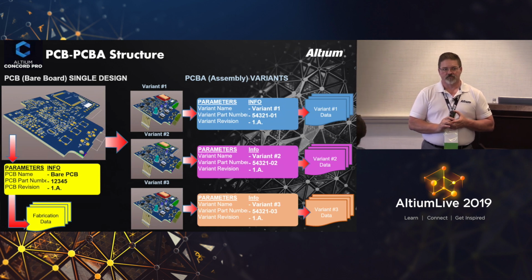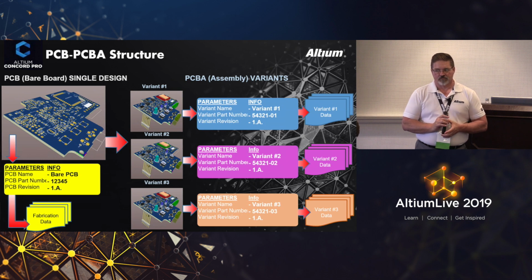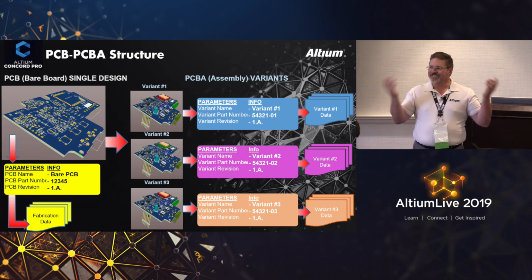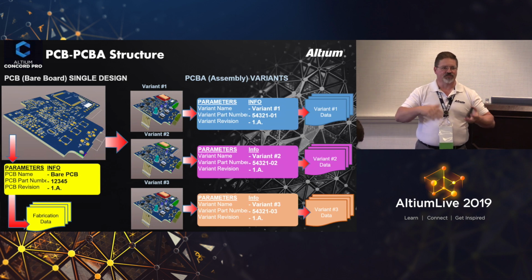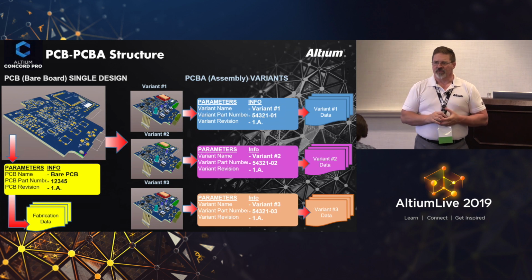In that case, the variants won't get new part numbers, but if we change the fab, the variants will get new BOMs because on their farm now they're using a different one. Right. The BOM would be updated. That's why you resync everything when you do a major revision on the PCB side. Everything gets resynced because now your BOM changes, because you have to update the BOM for your new PCB, and your schematic and all this.